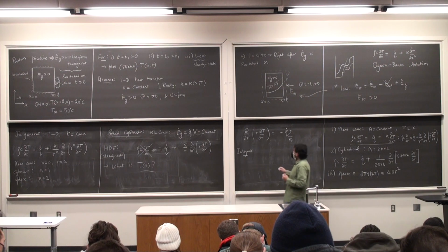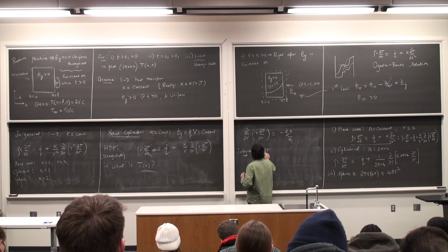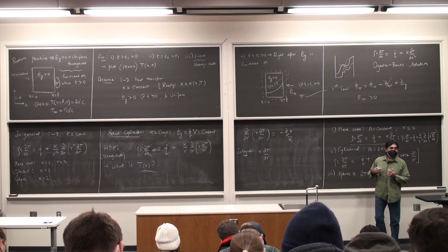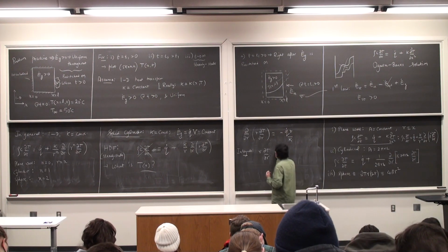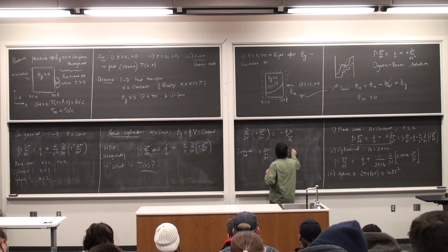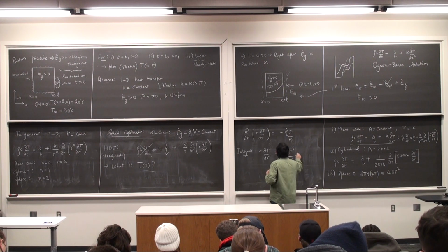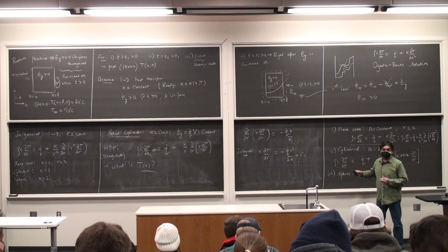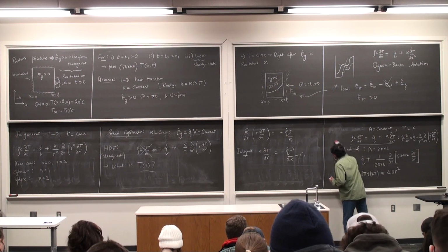So this is going to be r times dT by dr. I lose the first d by dr term. This is now going to be minus q dot r square by 2k plus a constant c1, which we do not know yet. Okay, bear with me for a few more minutes.